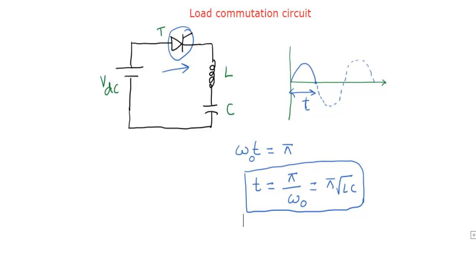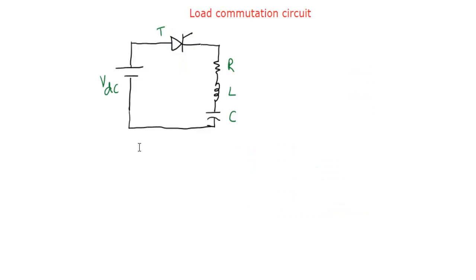Likewise, we can look at the underdamped system. Underdamped system means resistance, inductance and capacitance will all be there. Here the denominator of the second order system will be s square plus R by L s plus 1 by LC. From this, we can find the damping ratio del. How to find del?